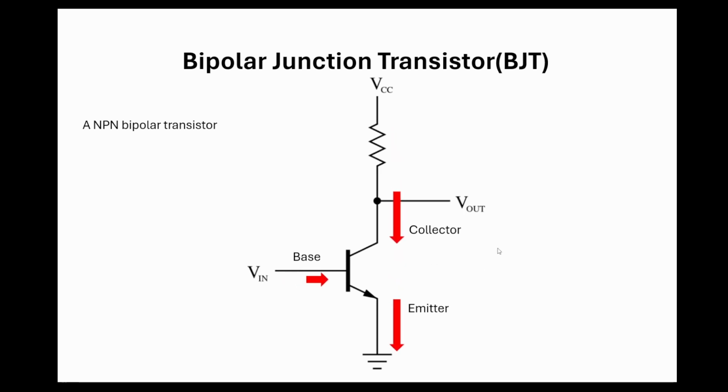So this is how the current flows through this specific transistor. Let's assume that the beta, or hFE, which is specified in the datasheet, is equal to 200. At the moment, we don't have a specific transistor, but if you have a specific transistor, you can find this value in the datasheet. And we know that on this specific transistor, the current on the base is 50 microamps.